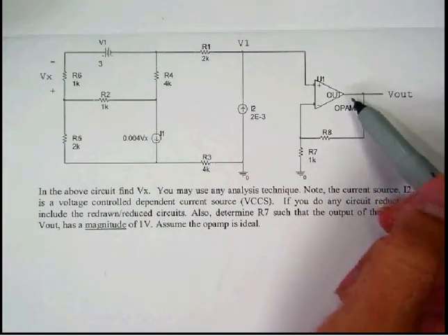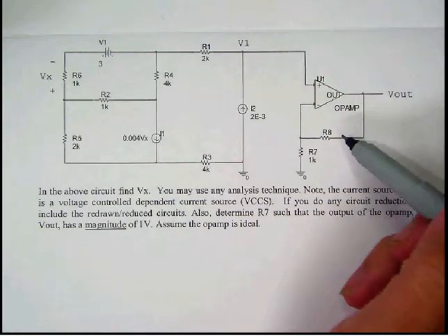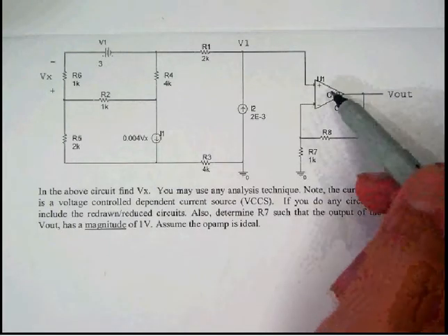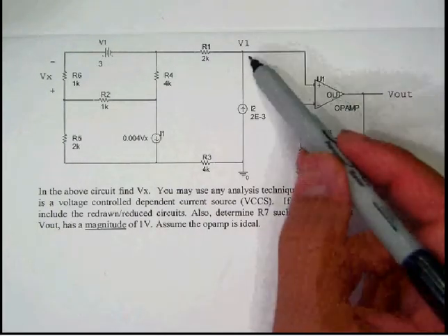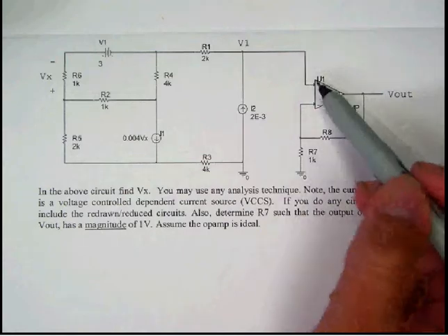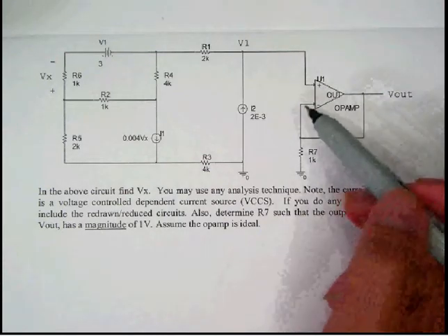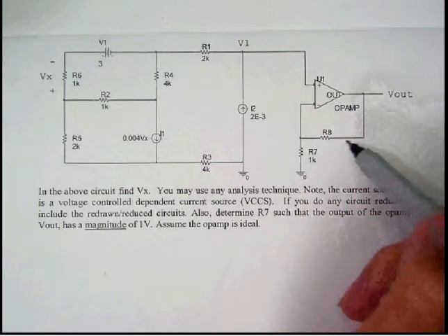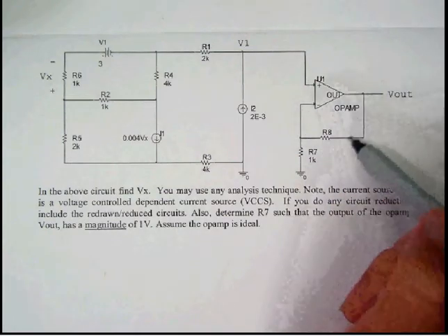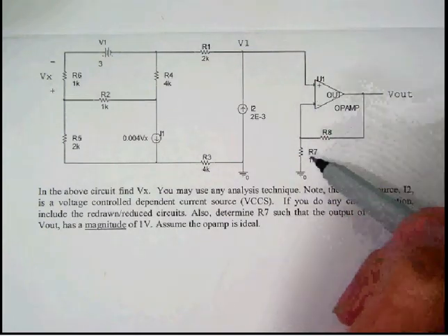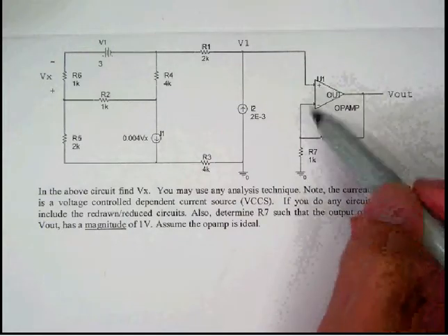So is it an inverter? It's not an inverter. You've got this voltage right here driving the positive input. So it's not an inverter, but it does have some negative feedback right here. So that's something to know. So we'll look at that as well.